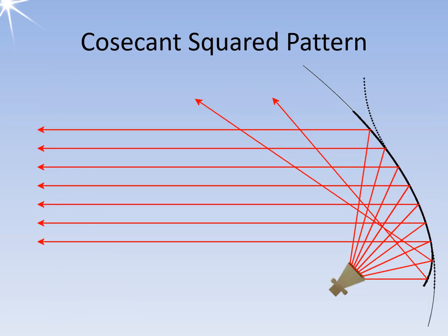Two reflector modifications can be made when designing a cosecant squared characteristic using offset parabolic antennas. One option is to bend the upper edge of the reflector backward, as shown by the dotted line in the picture. However, a more common modification is to bend the lower edge inwards, which results in a smaller and lighter reflector compared to the other modification.